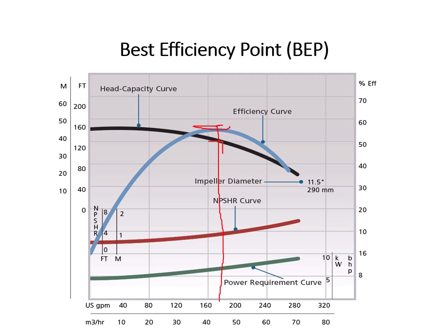corresponding to a best flow rate here, and make sure that your system flow rate is around here. Like you will have your system curve intersect your pump curve. For example, this is my system curve. I don't have it here, but let's see, this is the system curve.